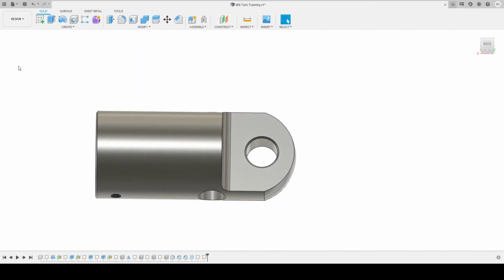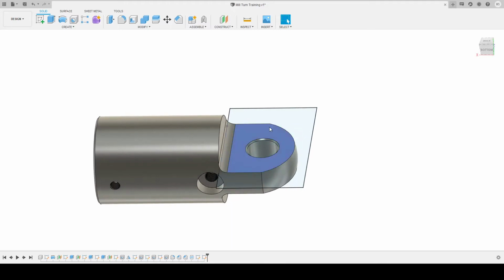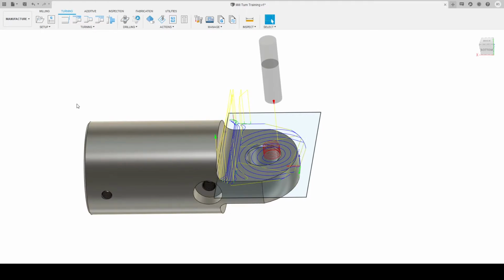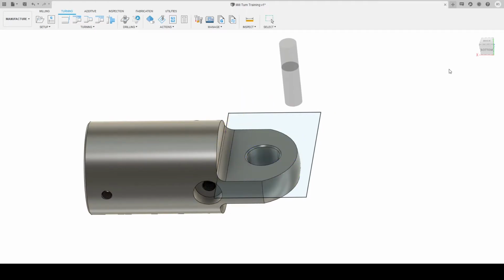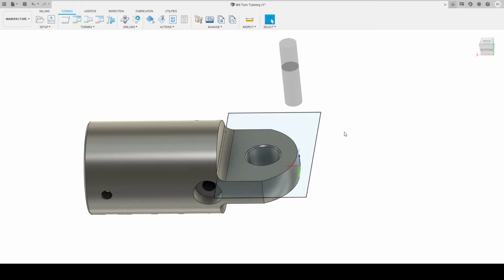Looks good. So we'll turn our sketch on. So we have a sketch sort of defining the boundary of where we want our toolpath to go. So we can edit our toolpath, go into geometry, and under machining boundary, under selection, we can unselect the chain that we previously selected, and now we can select this as a boundary. We'll see what happens now.